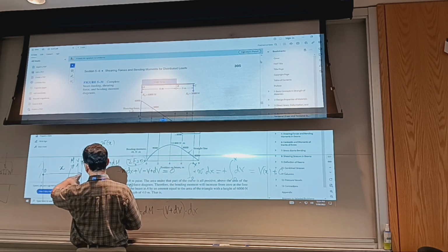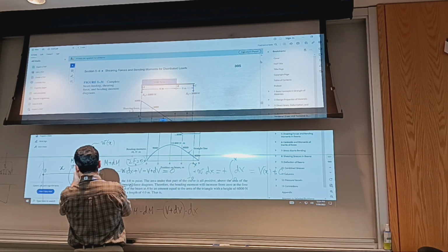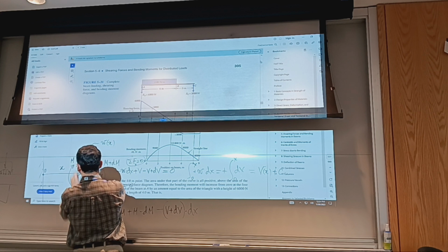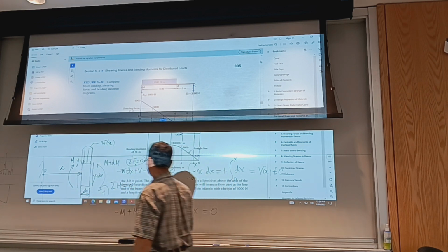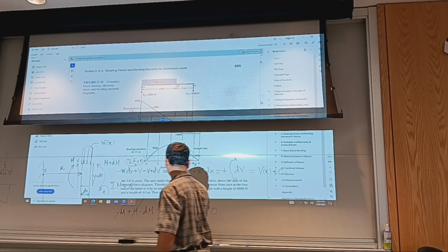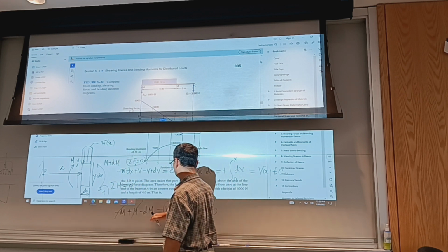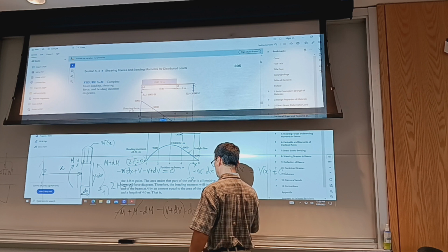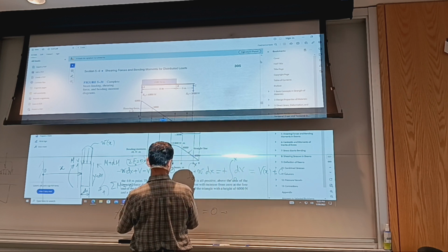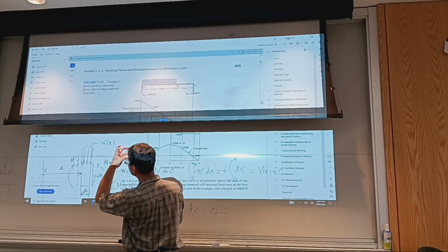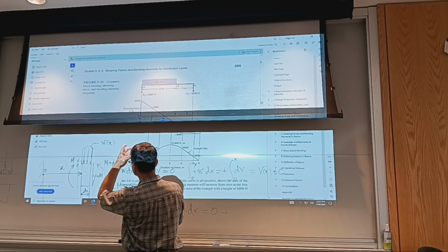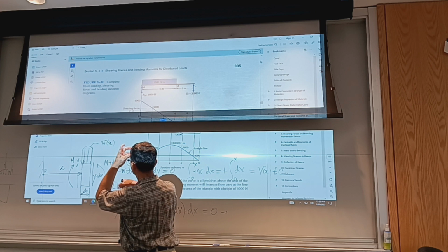So if I sum moments about this point, then this V by itself, the shear force, does not have an arm, but V plus dV has an arm of dx. All right, and this is equilibrium. So now M goes away, and I can relate now. So I'm just double checking the orientation of, so negative M, positive M.